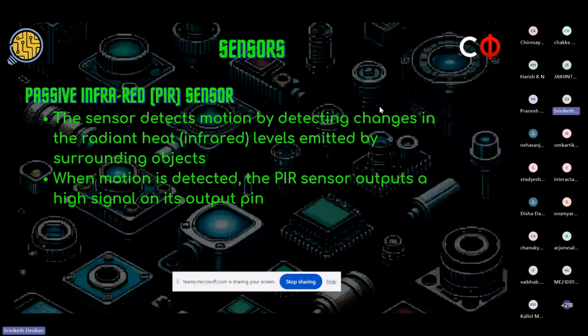If the radiation suddenly changes, there will be a quick current once again, and when the stable value of the radiation is read once more, the material will no longer discharge a current, and the sensor value will read zero. That tiny current generated by the material is amplified using an amplifier, which is then used to read a high value.